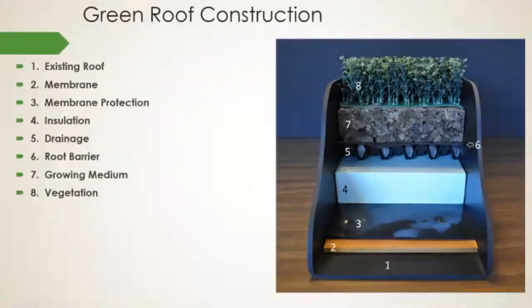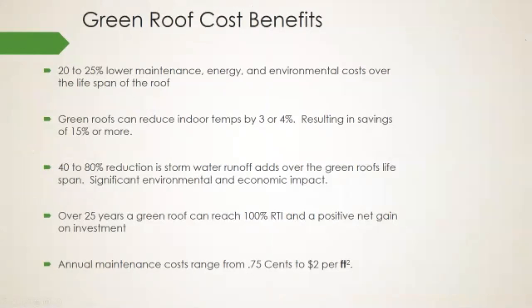And at the time, 2 pounds per cubic yard of slow release nitrogen fertilizer were also mixed in with the aggregate. So that would be something like a polymer coated kind of slow release fertilizer that was mixed in there. And so we still will broadcast some kind of slow release fertilizer in the spring on just kind of the ornamental things up there. So that's the construction.